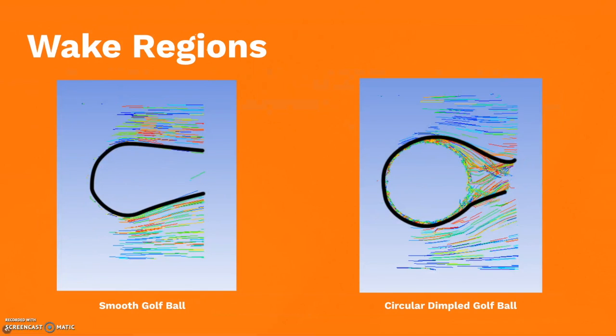Based on our results from turbulence, when we look at the wake region of the smooth and circular dimpled golf balls, we should be seeing results similar to what was described in the background section. That is, by having a layer of turbulence on the golf ball's surface, the separation point for the air should be delayed, resulting in a smaller wake region. The snapshots taken during the simulation prove that the expected result is indeed true. The smooth golf ball on the left ends up having a comparatively larger wake region than the dimpled golf ball on the right.